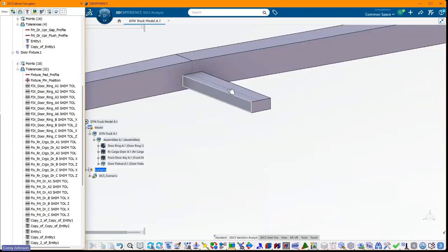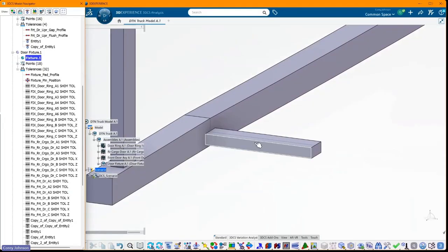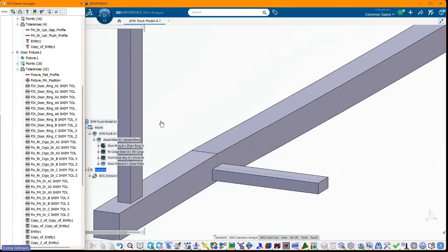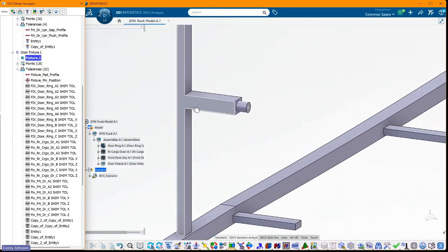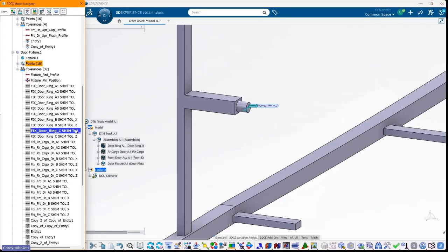And you'll notice if I zoom in over here and I get kind of a side profile view, I highlight that A5 and you can see that little arrow highlight, just a point in the direction that pad controls. And then likewise, if I scroll up here to this pin controls X and Z. So I have a separate X tolerance and Z tolerance. So pretty simple, just a point on each fixture point location. You just need to add a tolerance in each direction that it controls.